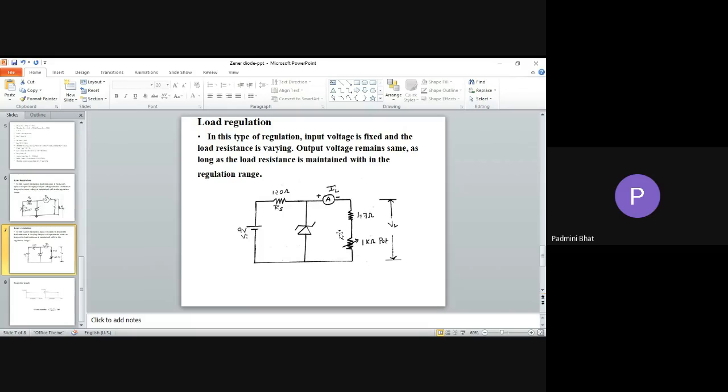When we see like that, this current value is varying. Then finally, after many turns, this pot comes to the maximum position. Now actually we should see in which range this current was almost constant. I don't get exactly constant, but almost constant. So whichever range I get almost constant, I should think that those are the load regulated loads.